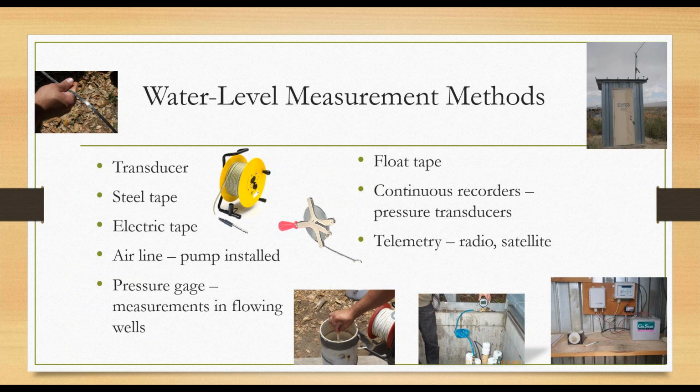But they are especially useful in an area where you have a pump installed or the water is actually pumping. The turbulence of the water will not really impact the measurement if you're using an airline. So the method can be used while the well is actually pumping, unlike the steel and electric tapes.